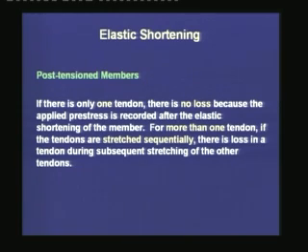In post-tension members, as the jack gets the reaction from the concrete member itself, when the jack is applying tension in the tendon, the member is shortening, and after the shortening stabilizes, we are recording the final force. Hence, we do not consider the elastic shortening as a loss because we are recording the prestressing force after the concrete member has shortened. This is true if we have just one tendon for post-tensioning the member.